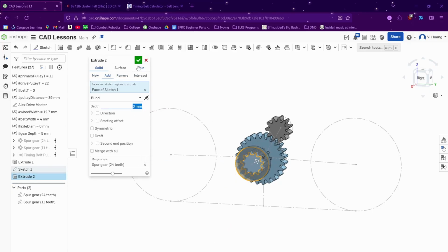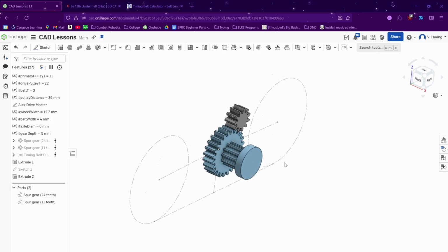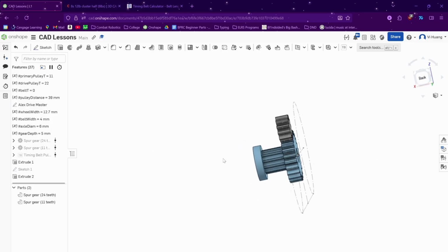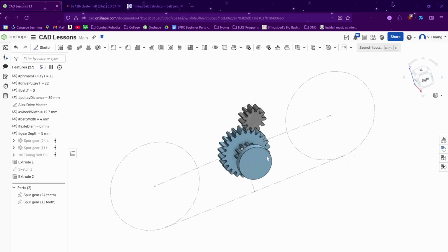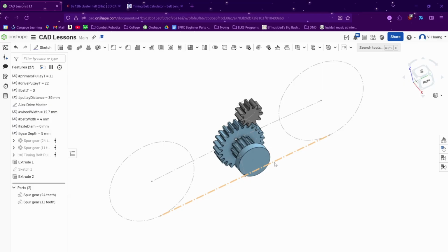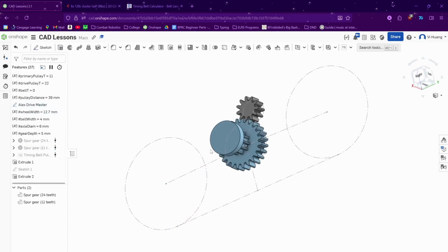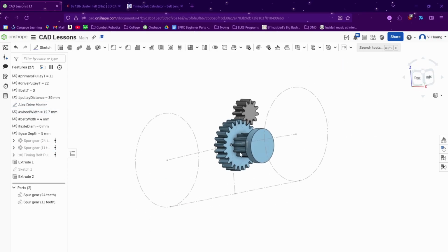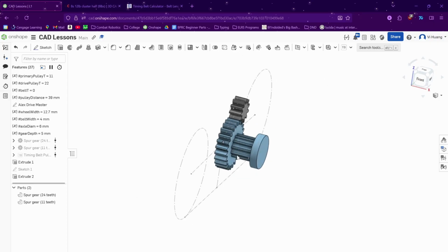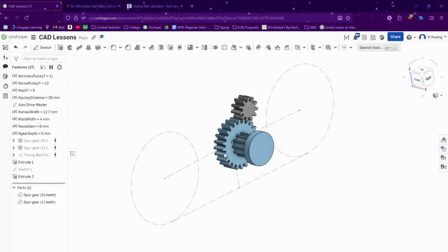And as I'm doing this, I want to talk about the pros and cons of parametric CADing. Especially when people first start out with parametric CAD, you might feel a pressure to do everything parametrically. It is an option, but in my experience, it's not the most efficient way to CAD. The most efficient way to CAD is to parametrically define a master sketch and then CAD semi-normally from there. Now that I have these two values, I want to go ahead and define my wheels.